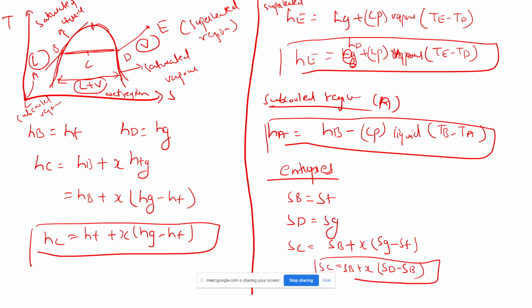Sir, so this Cp delta T is valid for any substance, even incompressible, but the Cp value alone changes like that. Yeah, Cp value will change. Temperature delta T will remain the same. Only the Cp value will be different for ideal gases and different for vapors. Okay, sir.